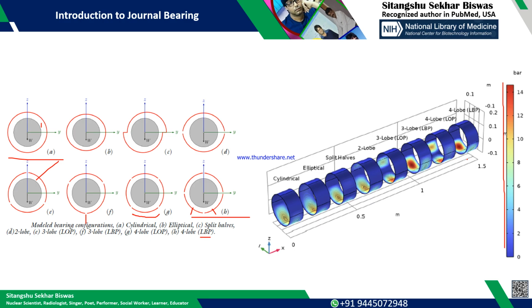This can take the radial load. And at the top of the pump, there will be the thrust pad, and in between there will be the liquid, which is basically operating as a hydrodynamic bearing, the operation which I have explained here.